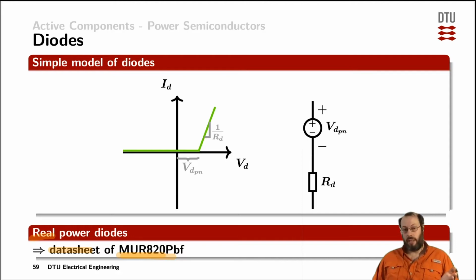Now, having a look at a datasheet is typically also the basis for a SPICE model. And as I have chosen three different levels of modeling a diode in here, if you start to drill deeper into actual SPICE models, you would also see various different levels on how they are modeling real power diodes. You can increase the effort of modeling until it fits your expectations, but at some point, the effort of getting an even more accurate model is starting to get more than it actually takes to build prototypes and measure what's happening in the physical lab.